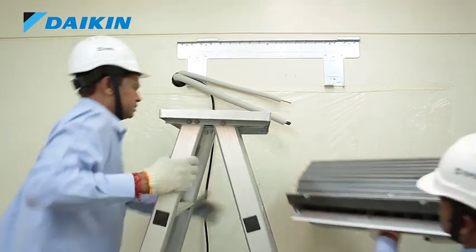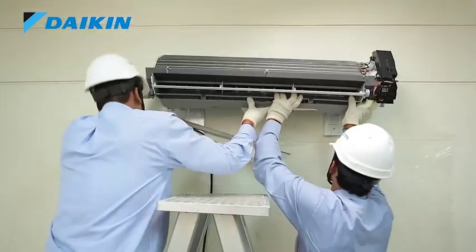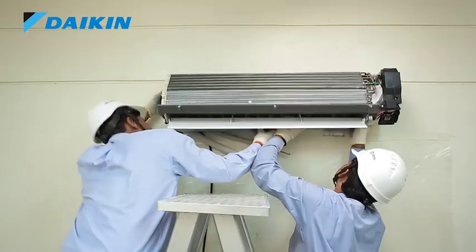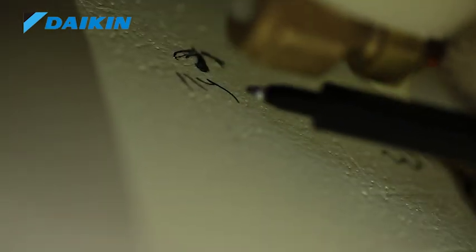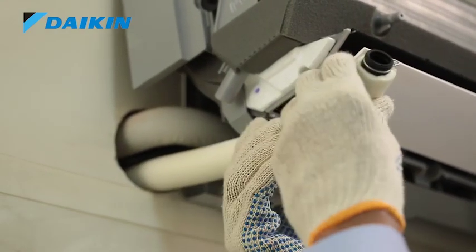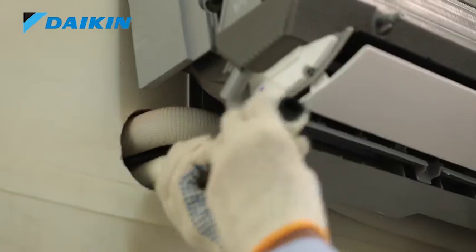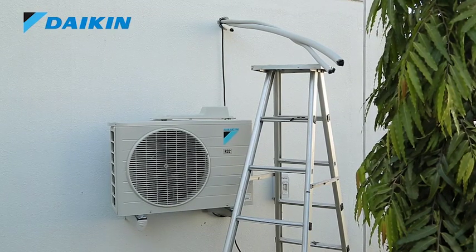Now, mount the indoor unit on the mounting plate and mark the position of flare joints on the wall. Take out this drain pipe from the wall hole towards the outdoor side. Also make sure that while passing the drain pipe through the hole, it must be placed below the refrigerant piping.